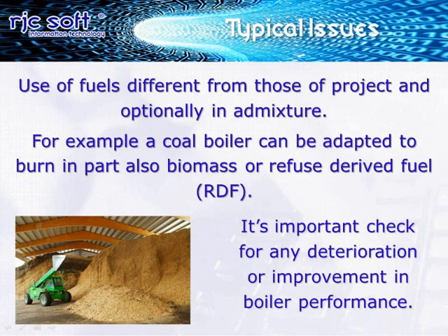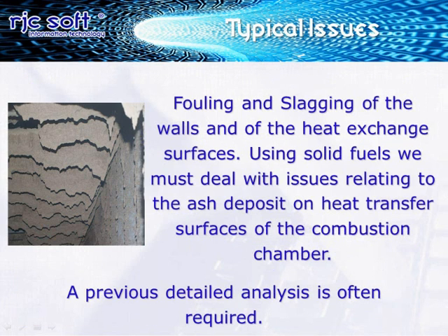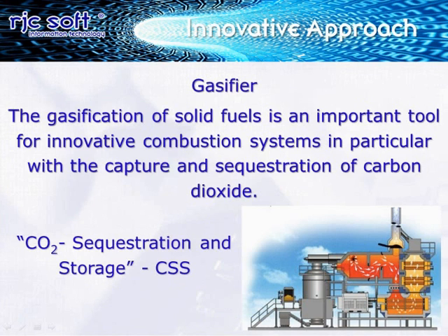A very important and often recurrent issue is related to fouling and slagging of the walls and of the heat exchange surfaces. Using solid fuels, we must deal with issues related to the ash deposit on heat transfer surfaces of the combustion chamber. A previous detailed analysis is often required. The IPSE code is also often used for the study of innovative combustion processes, for example, gasification.